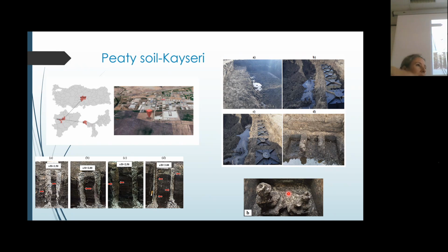He is working in the laboratory, preparing the columns, a single column or more than one column, with the load on top of it. Then they are also calculating the settlement that occurs in that area. Peaty soil is really problematic. You have a water content of 150 or so. It's kind of plastic, but there are fibers inside.